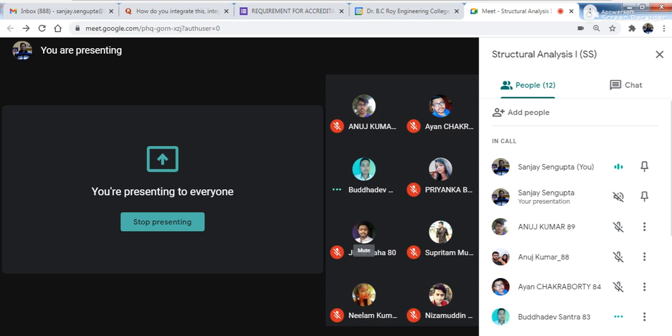Once you equate them, you get the equation of compatibility, because you know that because of this prop there is no deflection at this point, correct? So once you equate it, you only have this unknown, right? Only this RB is unknown to you.